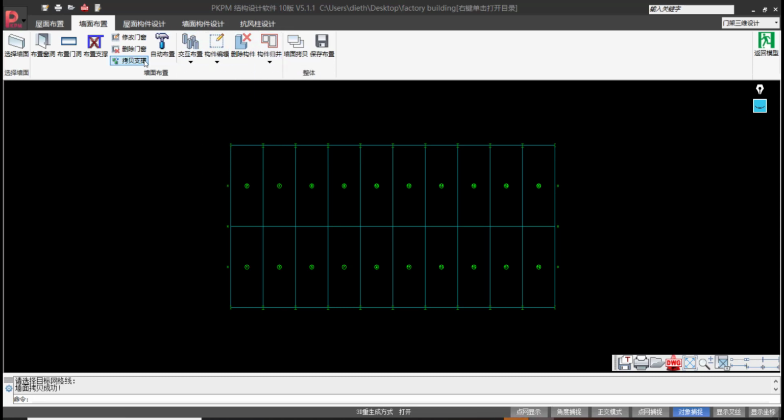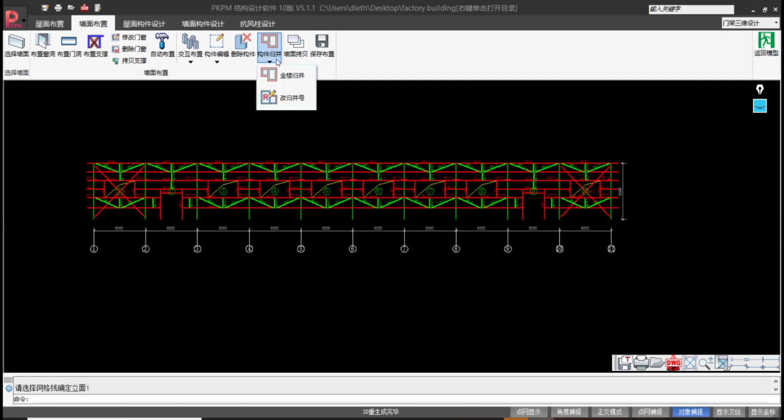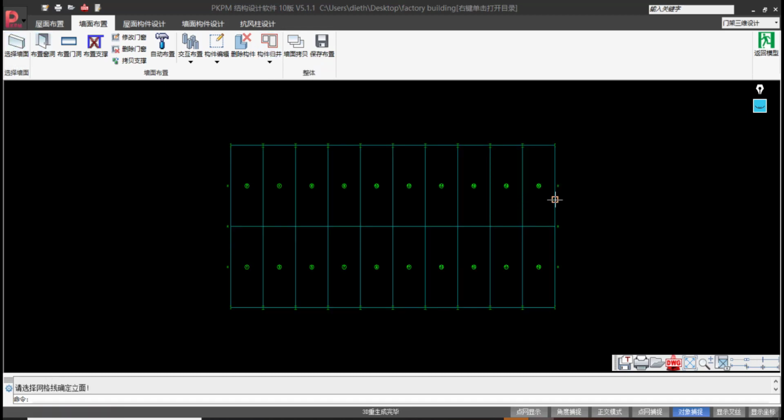Then after that I press on copy the wall. This time I want to copy this side to the other side. So I use this as my original. Then I'm copying up to this point. So it's done. Then I can go back to my 3D model. Actually, let me show you that it's been copied. I click on this to open up this wall, and we see that everything has been put in place. That's a shortcut that one can use to get the work done faster.